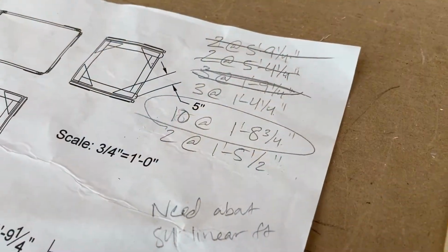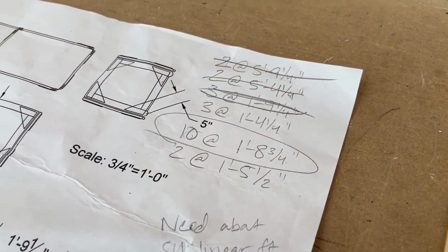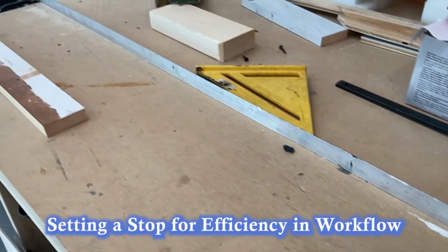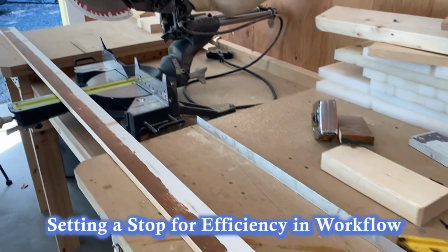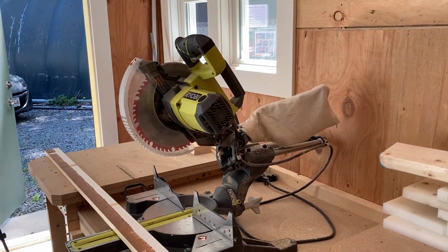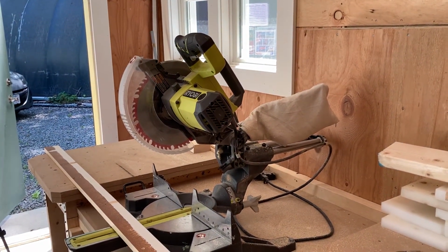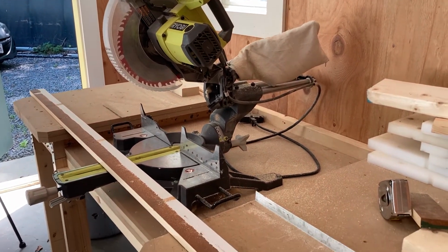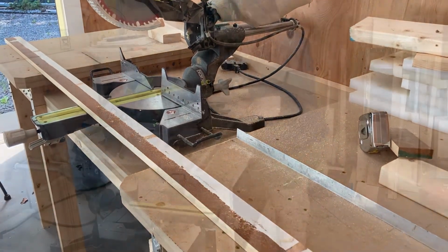I need to cut 10 pieces at 1 foot 8 3/4, and that's enough pieces to make it worthwhile setting up a stop along this fence. The fence is not really on the ideal side for this particular saw, given that I am right-handed and the tool is also very much set up for right-handed people. But I will go ahead and set this up and then I'll show you what I've done once it's arranged.